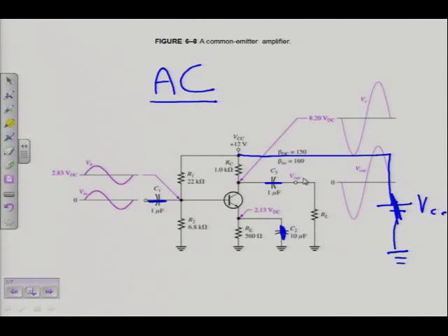Now I have to simplify the circuit so that I can see which of these resistors are in parallel and which are in series. Of course, I have to do some calculations about these resistances. The easiest way to approach this is with the 3 terminals of the transistor. So let's start with the base. And I can see here at the base, R2 is connected to ground.